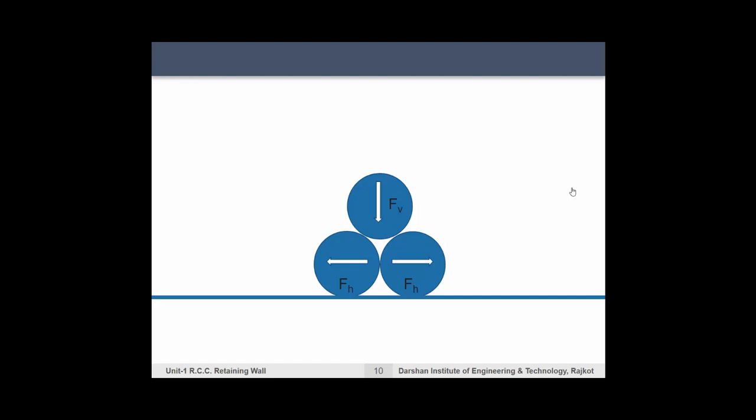The magnitude of this outward force depends on how hard the upper cylinder pushes downward, and that in turn depends on its weight and on the weight of the material that it supports. If the lower cylinders are constrained by a structure, they will exert a horizontal force on that structure.